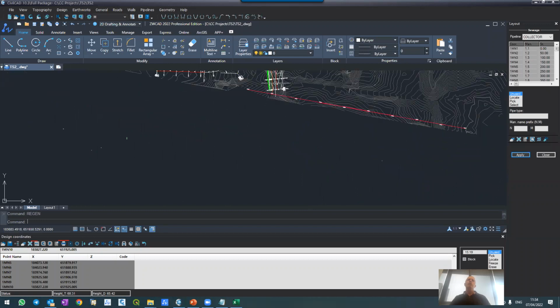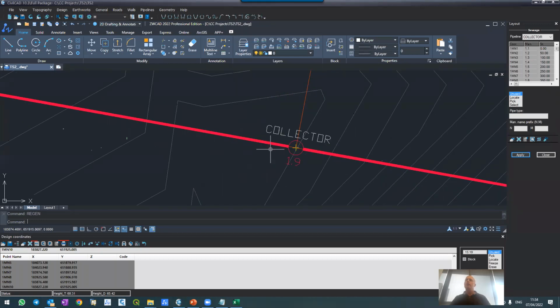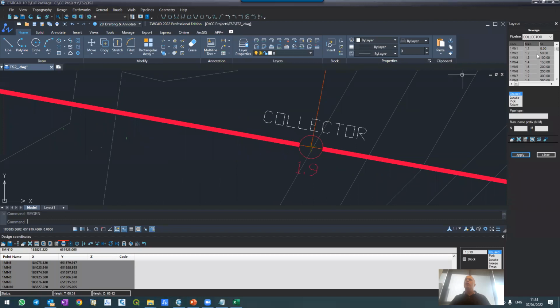What I'm going to do now, you see, I can move here on the right, and we have two more columns, pipe diameter and manhole diameter. So I'm telling the software this one is 600 millimeter. Remember, I chose to work with millimeters here, so 600 millimeter. Now I can choose to do it all over, or I don't need to, because once I do it in the beginning, it will project all over.